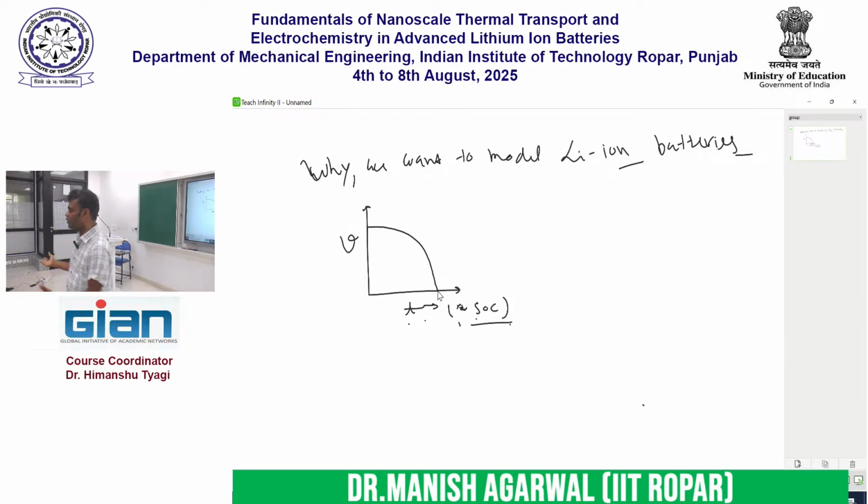You want to charge your battery as fast as possible, right? But why doesn't everybody just start charging the battery, just supply more current so it charges faster? There are ramifications to that. There is the theoretical capacity and the actual capacity that you get out of the battery in a particular condition, and that depends on the charging or discharging speed. So we want to know up to what charging or discharging rate we can draw a sufficient amount of power.